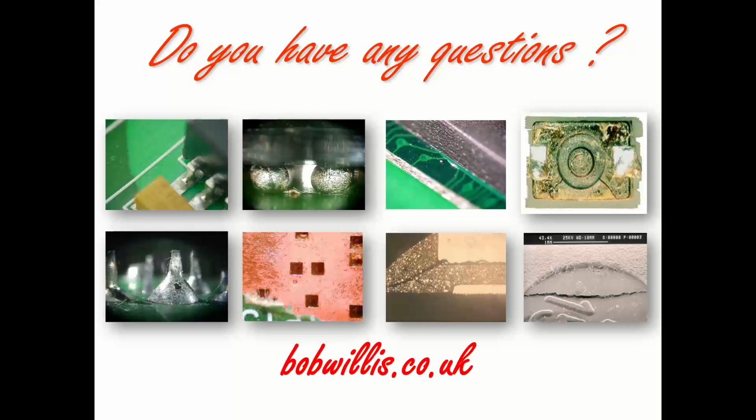It will not be an oven, obviously, because you can't put a decent camera into an oven, because that wouldn't work. But you can also buy what we call video simulators, and these are basically boxes which you can simulate the soldering condition, just like your reflow oven, with air or nitrogen, and you have cameras mounted into special glass ports within the system. So again, you can make videos in those ways.